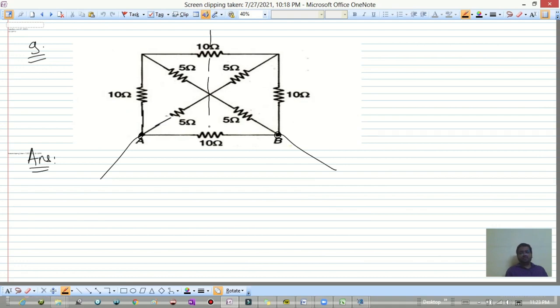As you can see, if you apply over here, the same thing is there. That is the symmetric circuit, right? So V by 2 and minus V by 2 method, yes, you can apply. So in this 5 ohm, if it is dropped by minus X, in this 10 ohm, plus X, in this V by 2 will drop by plus X, in this 10 ohm, it will drop by Y, minus V by 2 will drop by minus X, and this is minus Y. So this indicates at this point we have 0 volt, then detach this along this line, and it will become a very simple circuit then.